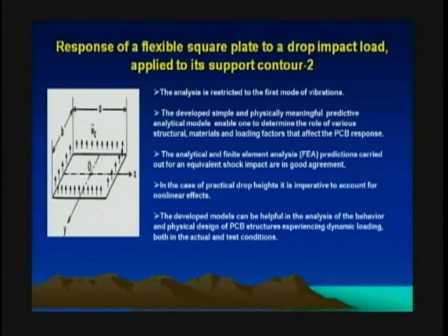This estimate, I'm still planning to do that. I haven't done that yet, but I would say that it's much higher. It's probably 90, maybe more, percent of energy is due to the first mode of vibrations. Therefore, we can make our complicated life, which is hard regardless, a little bit easier if we consider only the first mode of vibrations. And by the way, you'll see here that finite element indirectly, maybe even directly, confirmed what